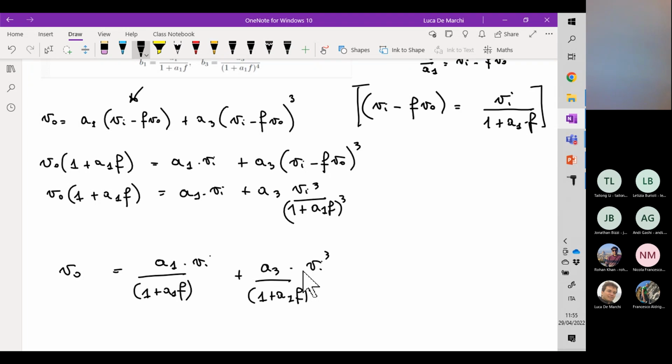Then we start to experience the influence of P1, but luckily, when we get to the new omega null, we have the phase curve at minus 135 degrees, which means that the new phase margin is equal to 45 degrees. Okay, so the circuit after the addition of the dominant pole is indeed stable. The phase margin is positive. So this is very important.